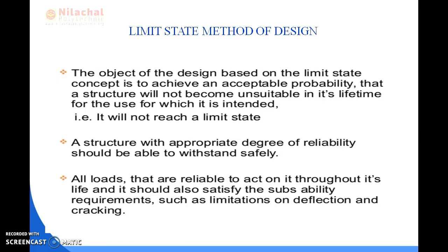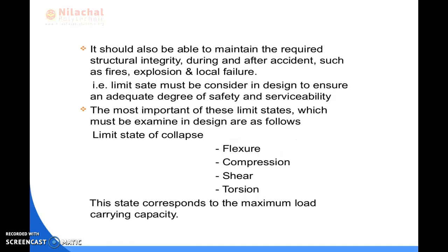A structure with an appropriate degree of reliability should be able to withstand safely all load conditions that are liable to act on it throughout its life, and it should also satisfy the serviceability requirements, such as limitations on deflection and cracking. It is the objective of design by the limit state method.